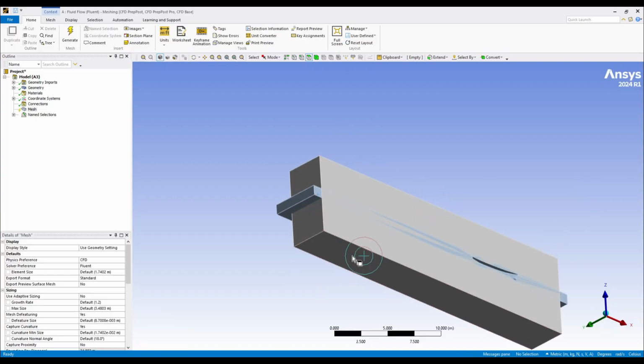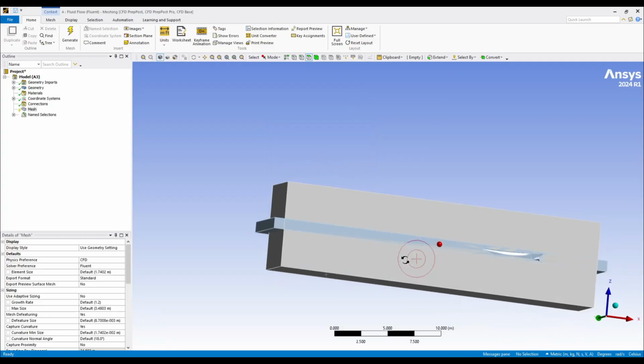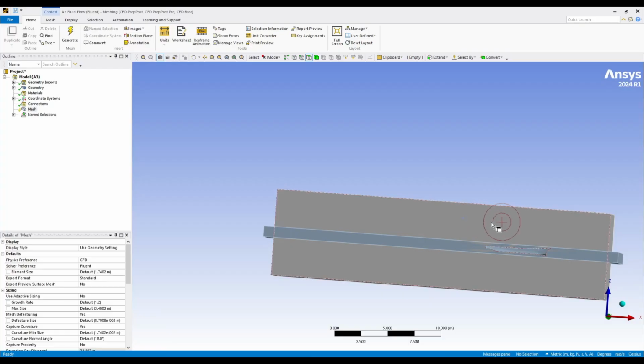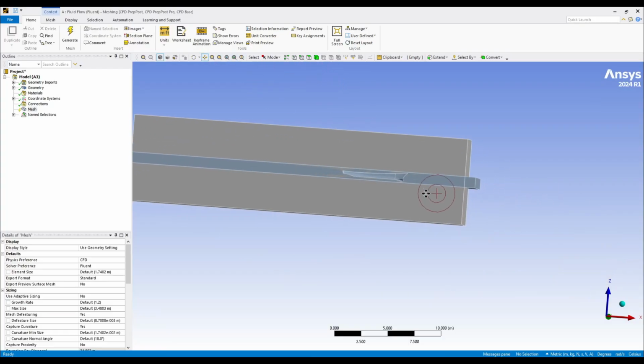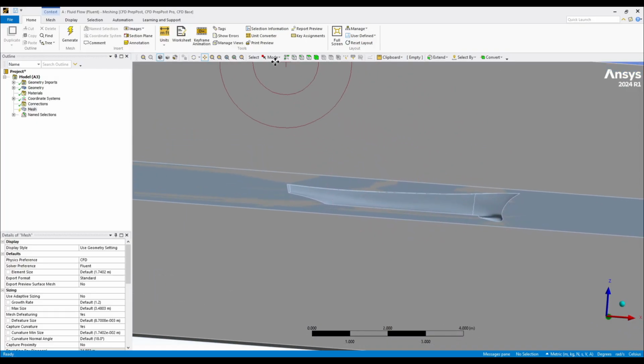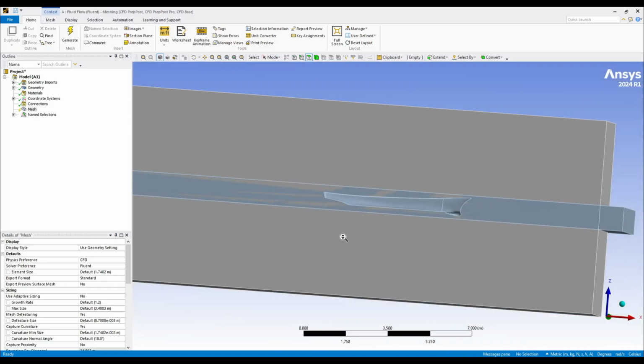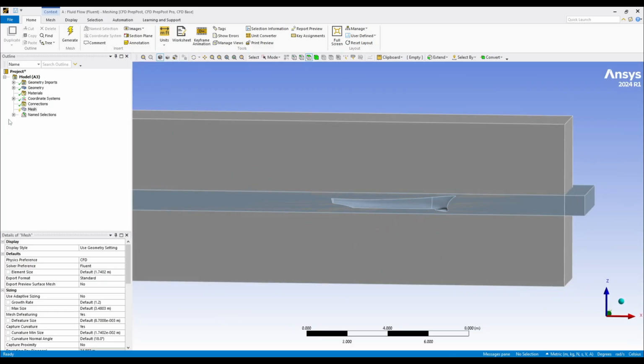And I'm declaring this bottom segment as the wall. And I'm also declaring, in order for me to select the hull, I have to go in a very sensitive manner in which I have to box select, and yeah, then my hull will be selected. Here I can declare this is hull. Now we are done with the naming. Here you can see the consecutive naming part.